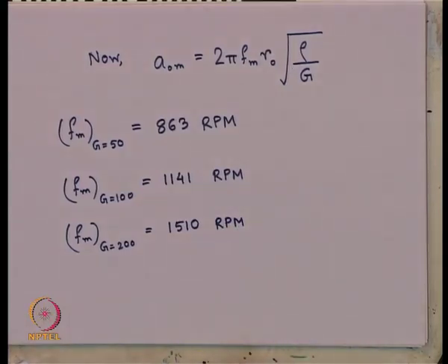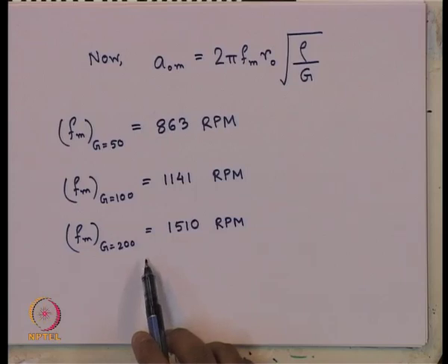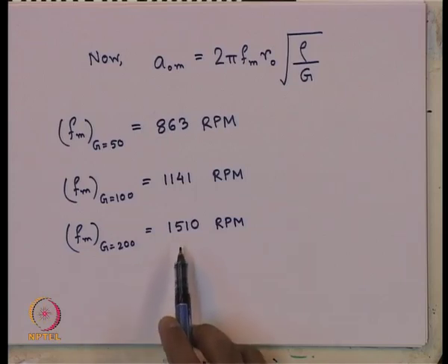So, remember, when the same foundation we are planning to operate at an operating frequency of 1500 RPM, for this third type of soil, usage of it is ruled out, because the operating frequency then will be very close to the resonant frequency, which should be avoided as per the design criteria.